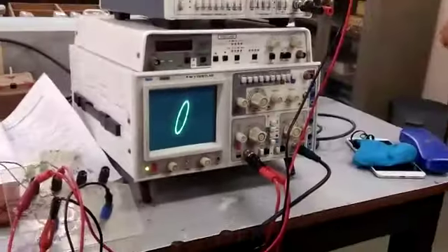There is one formula, phi, which is nothing but my phase. Phase is equal to sine inverse of x1 upon x2. Put the values of x1 and x2, then take the sine inverse of that value, then we get the angle. You can calculate the phase on this calculator.